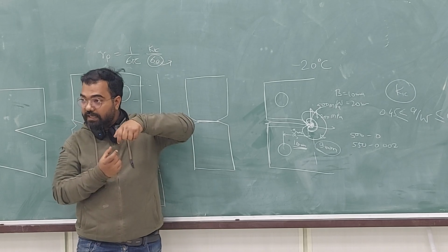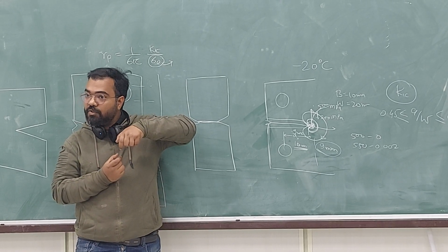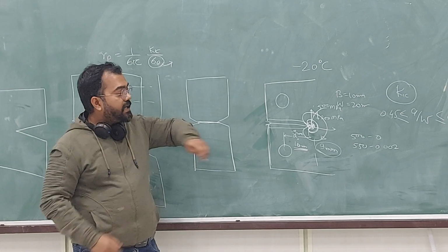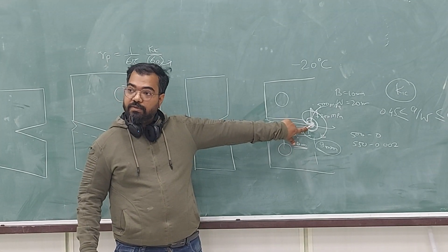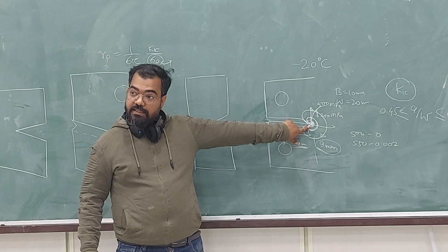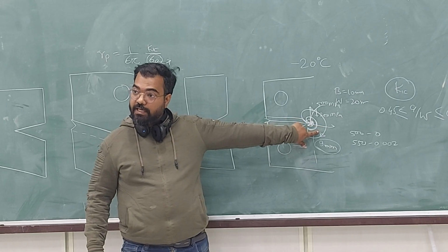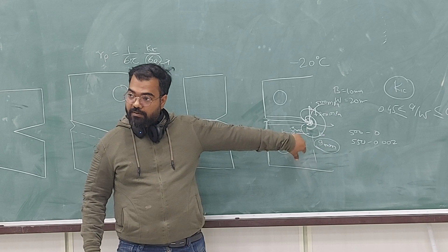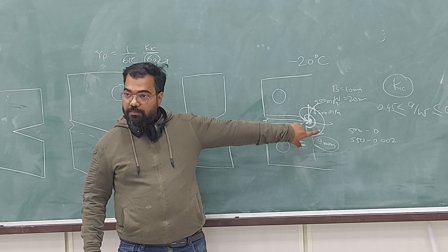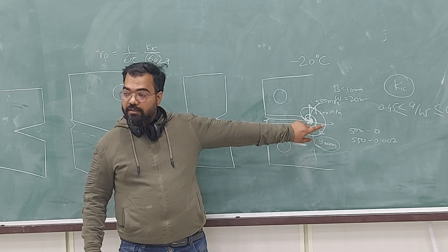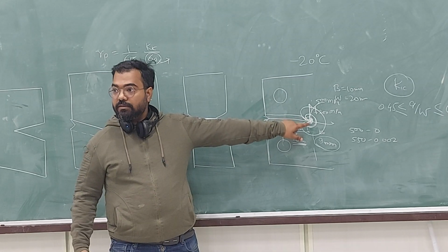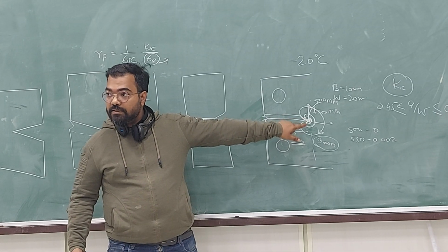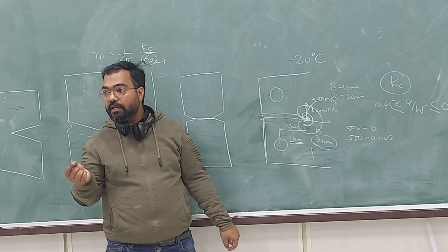When you are really doing the K1C testing, you have to apply such a load that the plastic zone which forms because of monotonic loading during the K1C testing must be larger than the plastic zone which you created during fatigue pre-crack. If the plastic zone during monotonic loading is smaller than fatigue pre-cracking, then it is not really K1C testing, because you are not testing the real material.